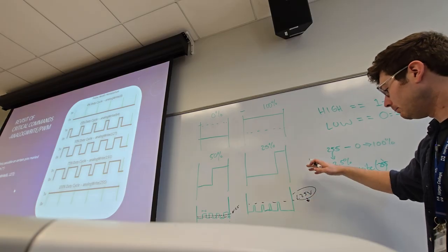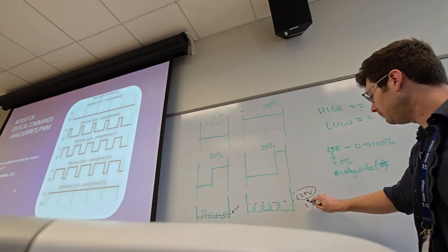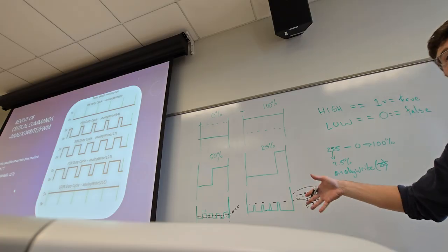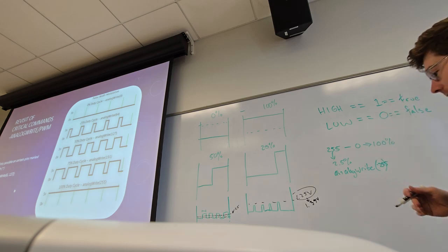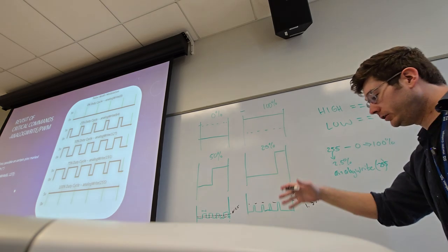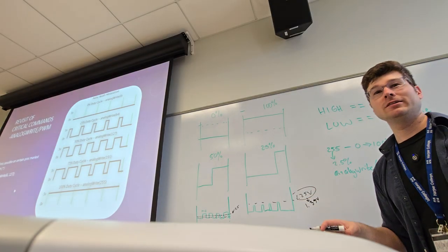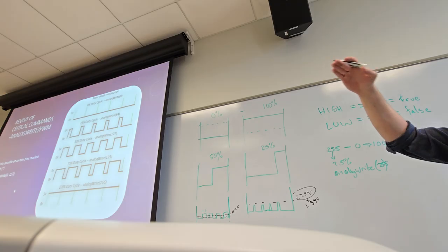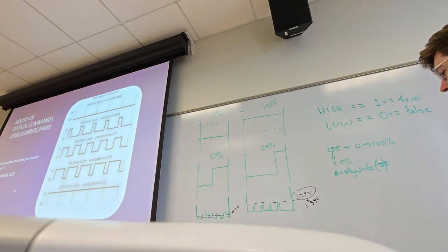So if we do a blip more, 2.5%, we could maybe get to 1.35 volts and have that kind of granularity of control. That's what it's all about. If we change that signal fast enough, 1 millisecond we play this voltage, the next millisecond we play that voltage, we can get sound playback, with specific intensities of analog output going to a voltage signal.